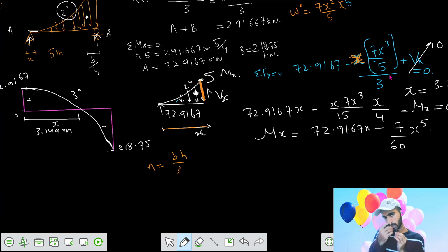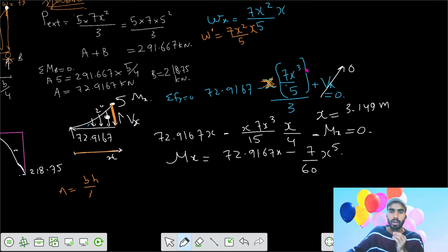Then we can say divided by 7. We got some value. We have to divide it by 1 by 4 power 3.5. Yes, we got the value. This one is your x power 4, the final value of shear force at x power 4. So we can get the value of x where shear is zero, equal to 3.5355 meter.